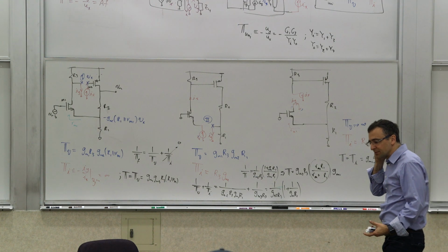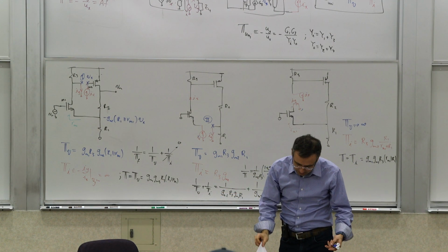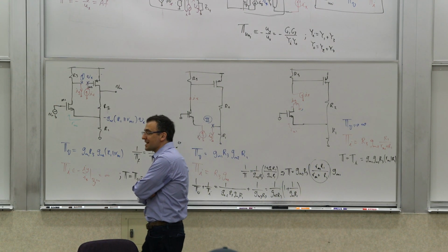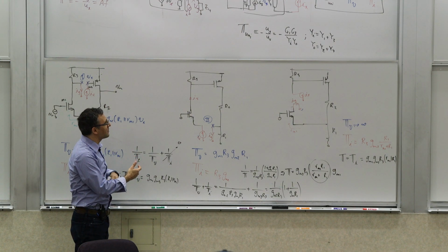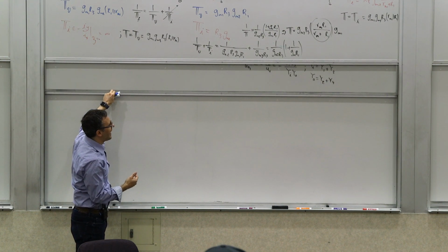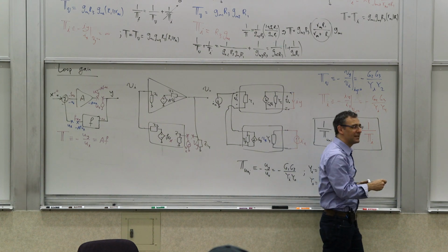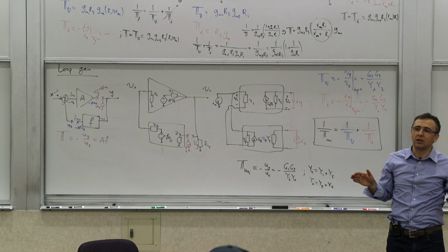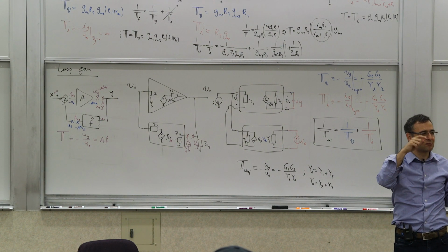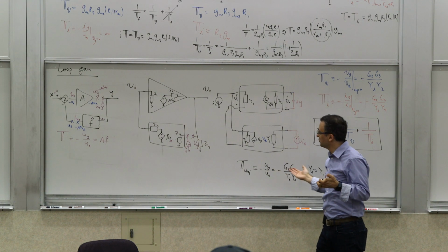So what's the point of this? First of all, we demonstrated that this is true. I mean, as an example, it doesn't prove anything. But it shows you that if you use this expression for the unilateral loop gain at least, you can calculate the voltage loop gain and current loop gain independently, and you don't have to worry about the loading, which is a big thing, because a lot of times in reality, these loop loading calculations are a mess. You don't need to do any of that.